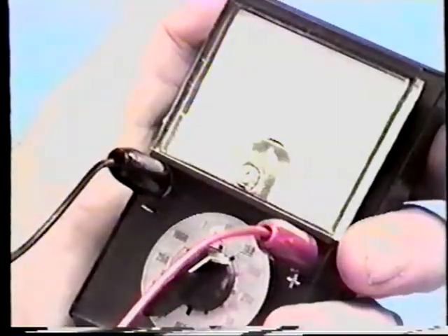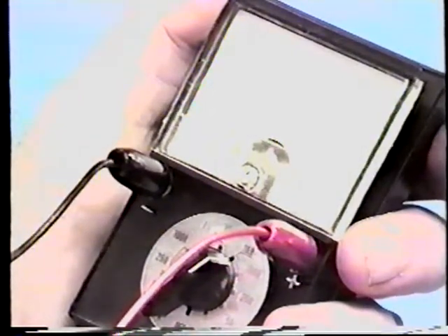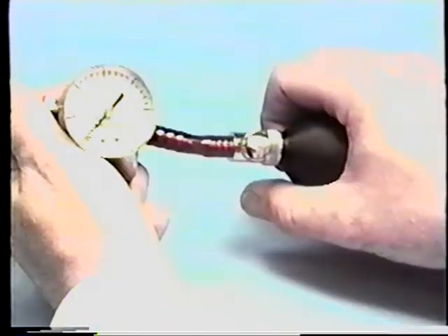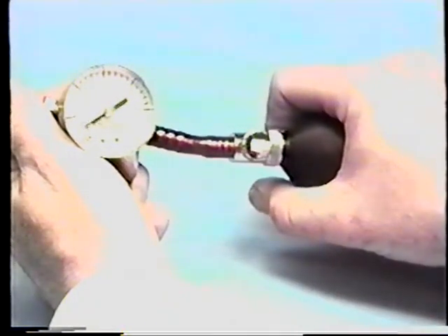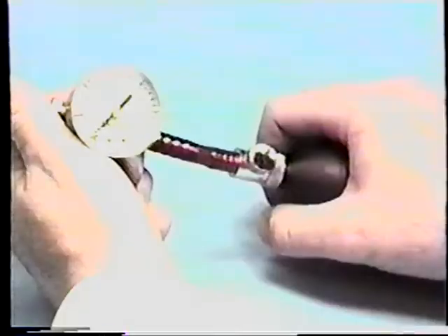The ohms meter reads infinite resistance between common and normally open, with no air pressure on the signal input. Slowly raise the air pressure on the signal port until the switch makes and the meter reads 0 resistance. This is the switching pressure. Now, raise or lower the adjustment as needed and repeat the procedure until the proper switching pressure is achieved.